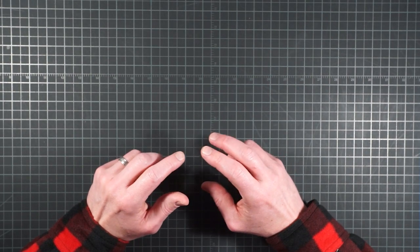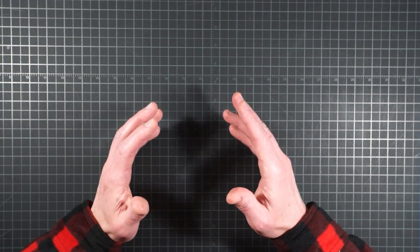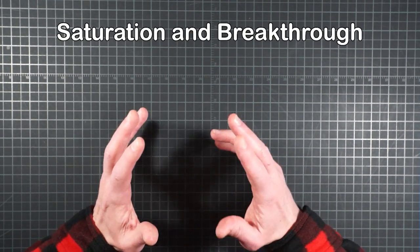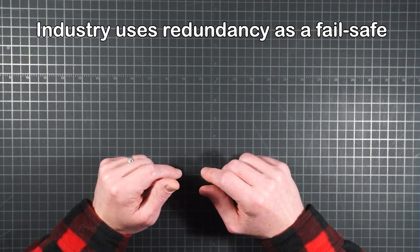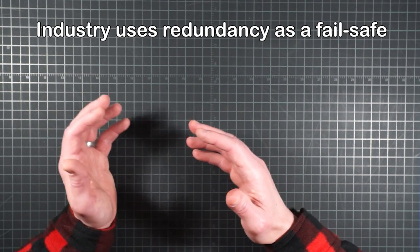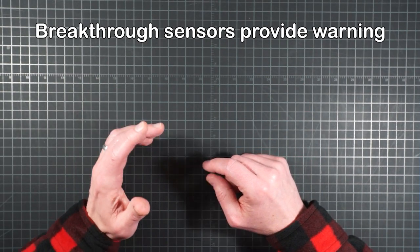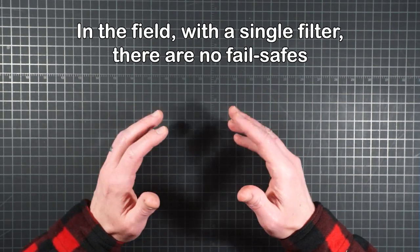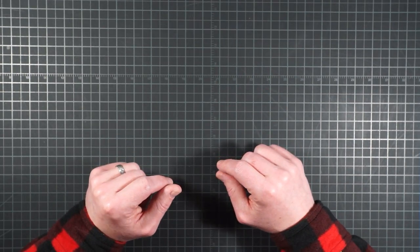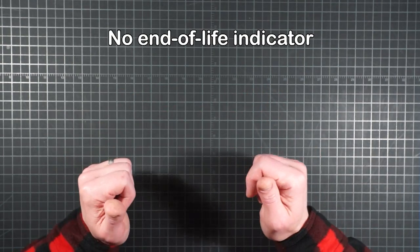So, what can the backcountry traveler take away from all this discussion of industrial water treatment? Saturation and breakthrough are real problems. So in order to manage such systems safely, the professionals use redundant systems as backups to provide fail-safes against eventual leakage. And they also employ specialized sensors to warn when it's time to replace exhausted units. In the field, with only one element, you have none of those precautions to save you. So to compound the situation, this type of filter has no actual end-of-life indicator.